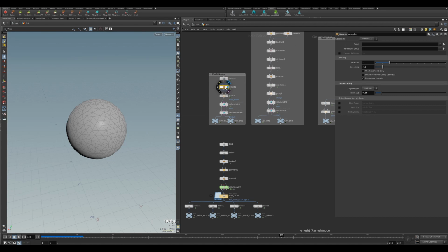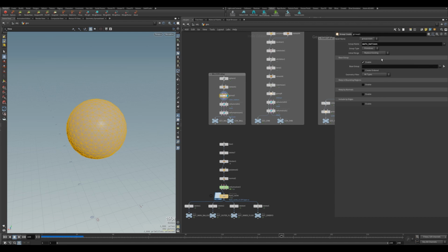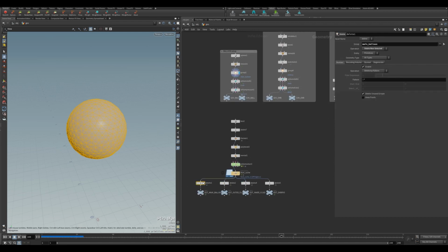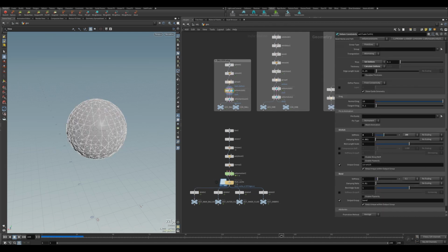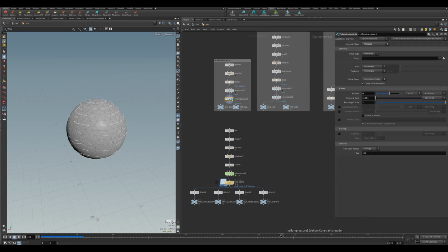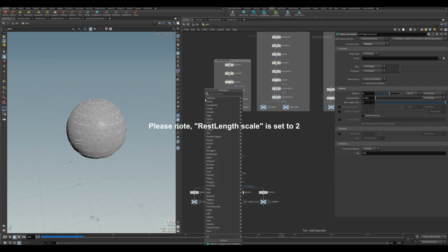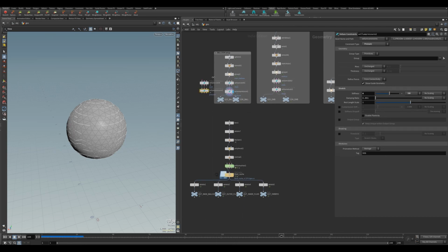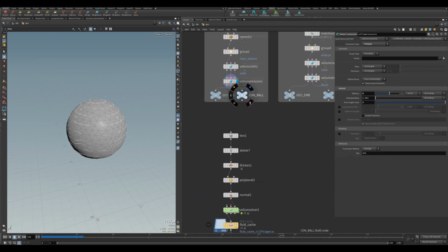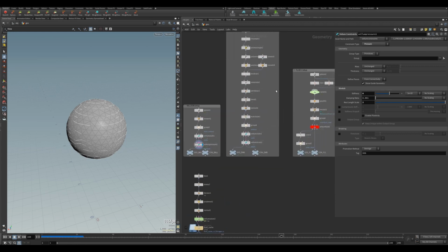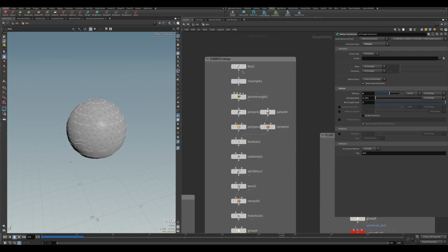And then I'm remeshing it because Vellum likes remeshed geometries. Then I'm creating a group called main balloon, which I will use later on down here in the delete. And then creating a vellum cloth, which is standard except for the stiffness is slightly different. And then vellum pressure, which is also standard except for the stiffness. If you type in vellum balloon, you'll basically get these 2 nodes. I'm calling it geo ball and constraints ball. So let's move on to the second setup, which is the embryo setup.